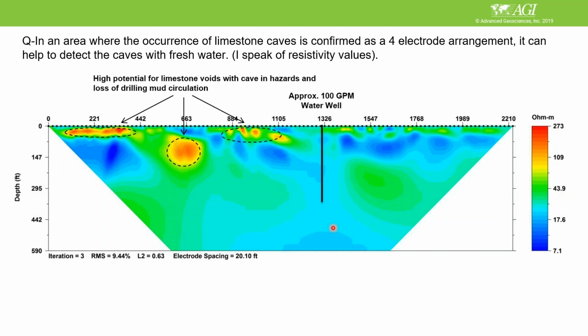I have one client who does lots of groundwater investigations, and at the beginning he was always doing vertical electrical sounding. Their success was less than, let's say, 30 to 40% when they did vertical electrical sounding. Later on they switched everything to the multi-electrode system, and they still do groundwater investigation. But their success after that with 2D investigations, believe me, is more than 90%.